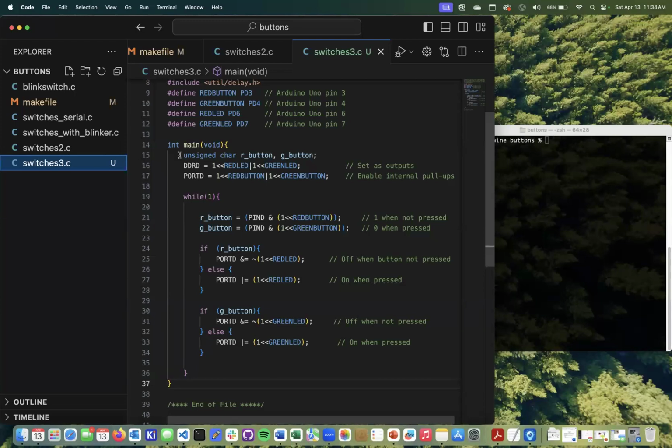And those are going to just be the status of the buttons, whether they're pressed or not. And now, you'll notice that you have some things that are done in capital and things that are done in lowercase. A rule, this is not a coding rule, but it's a style rule, is that whenever you're doing a defined macro, you do all that in all capital letters. And then when you are defining variables, you use lowercase. That way you can quickly see which is a variable and which is a macro.